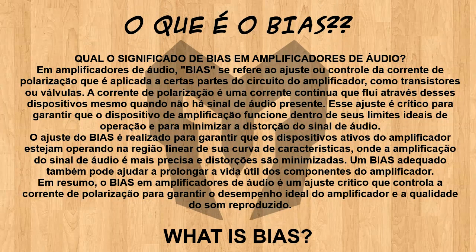What does bias mean in audio amplifiers? In audio amplifiers, bias refers to the adjustment or control of the bias current that is applied to certain parts of the amplifier circuit, such as transistors or valves. Bias current is a direct current that flows through these devices even when there is no audio signal present.